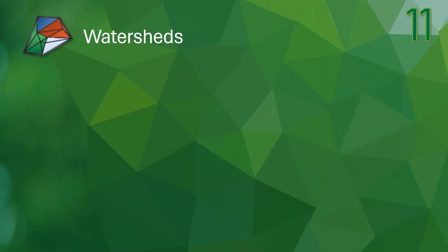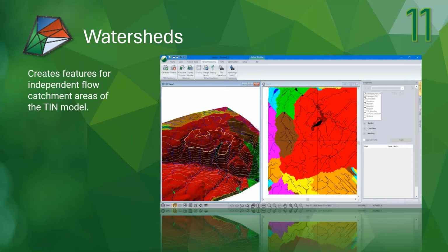So the tools themselves, watersheds. If you were with us for our version 11 preview a few weeks back, I am reusing some of the slides, but I just wanted to include them at a high level from an understanding perspective, especially for our new folks here today. So we've got watersheds. This is a tool that allows you to create features for independent catchment areas on your tin surface. This can be really important for knowing the locations of watersheds for drainage management and understanding as well how you can minimize the environmental impact of your road, especially if you end up modifying some of those watershed boundaries with your road surface.